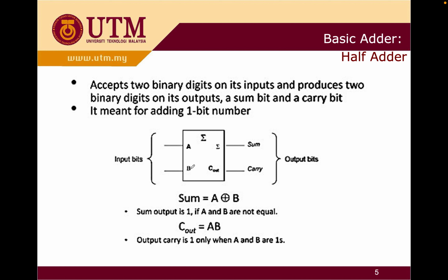Okay, in our basic adder, if you still remember, I asked you to remember the Boolean expression, especially for the sum and the carry. Oh, before that, on the half adder, and similarly for the full adder, you need to know the block diagram, how it looks like. How many inputs it has, how many outputs it's got, right, on the half adder.